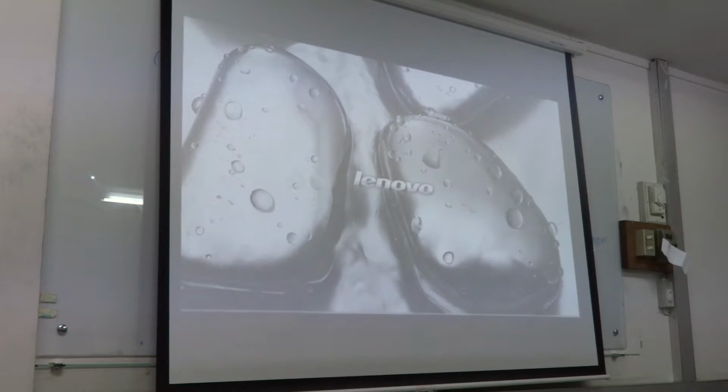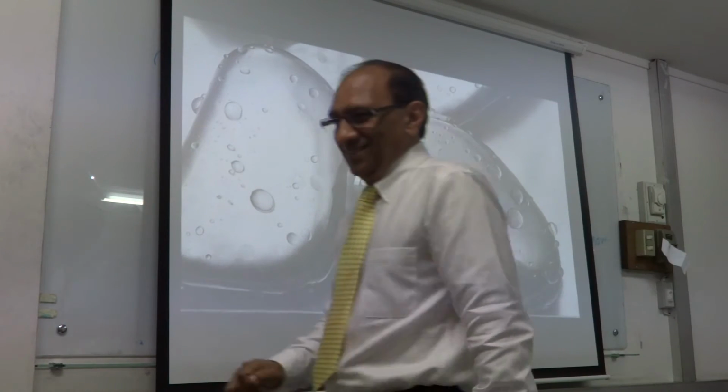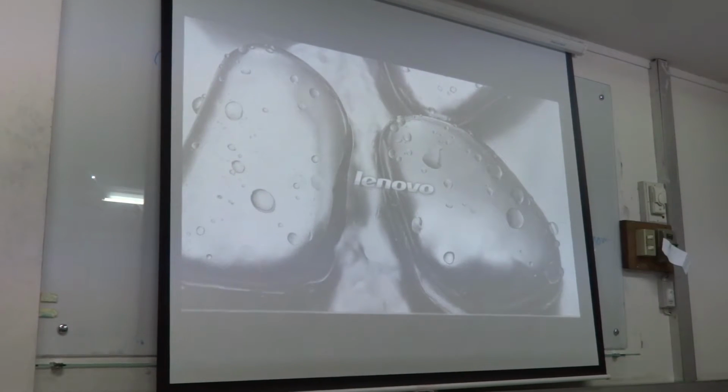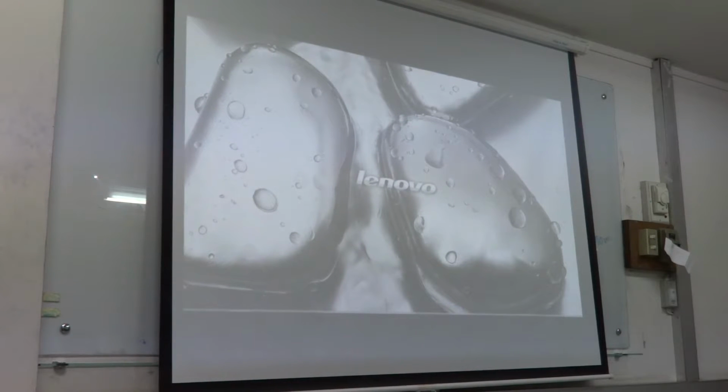So when you have torsion, you calculate the vertical components and horizontal components and add them as shear reinforcement, and you calculate the longitudinal component and add it to the longitudinal bars. So it's really complicated because you need to add the reinforcement in many places. And that is why people do not like torsion.